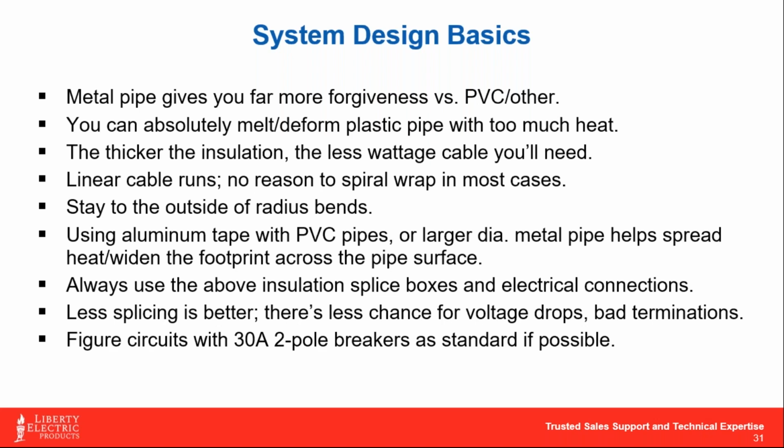So we talked about above insulation splices and electrical connections. Less splicing is better. Another tip we would give you is to always voltage check after your splice connection, to ensure you're getting proper current ampacity to the rest of that run. That's exactly why we try to reduce the number of splice connections, because if the electrician digs a little too far into that bus wire and cuts out a few of those strands, you're not going to carry as much current through it as you would if you never spliced it at all.